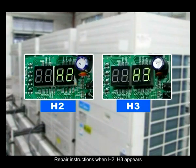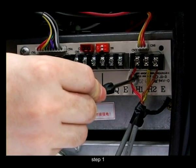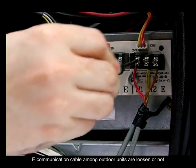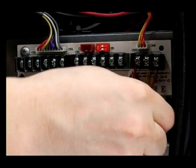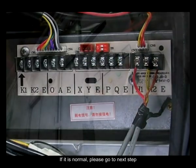Repair instructions when H2, H3 appears. Step 1. Check if the terminals of H1, H2, E communication cable among outdoor units are loosened or not. If loosened, please rewire the cable reliably. If it is normal, please go to next step.